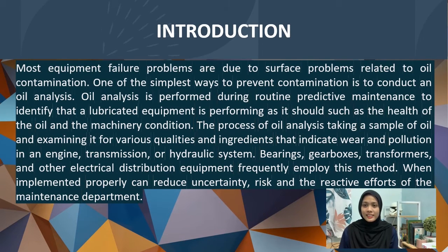Oil analysis is a routine activity for analyzing oil health, oil contamination and machine wear. The purpose of an oil analysis program is to verify that a lubricated machine is operating according to expectations. When an abnormal condition or parameter is identified through oil analysis, immediate actions can be taken to correct the root cause or to mitigate a developing failure.